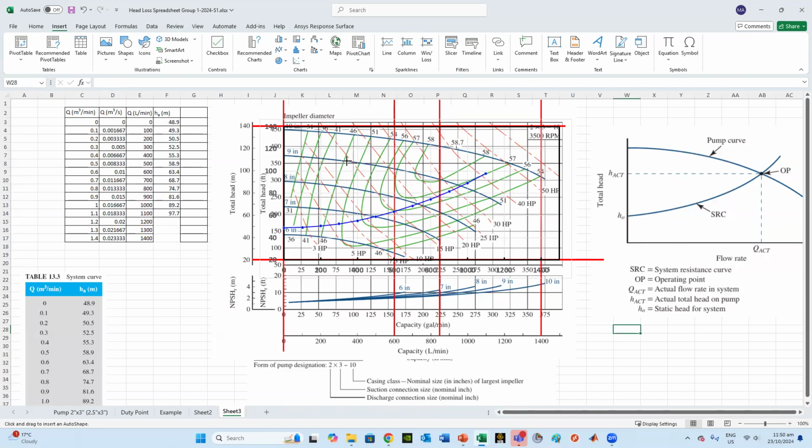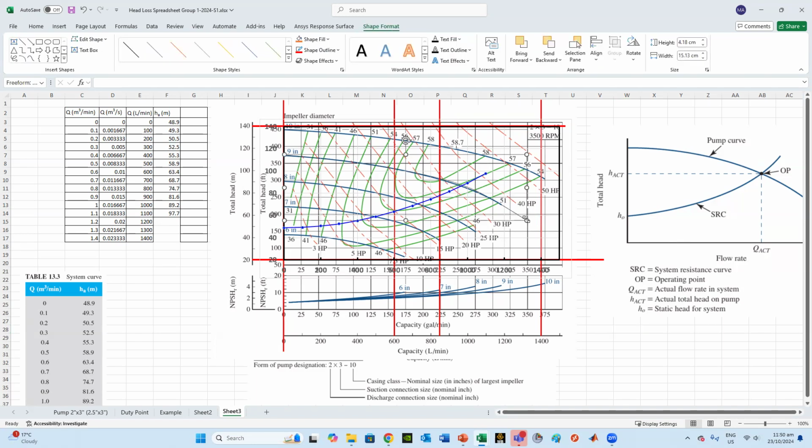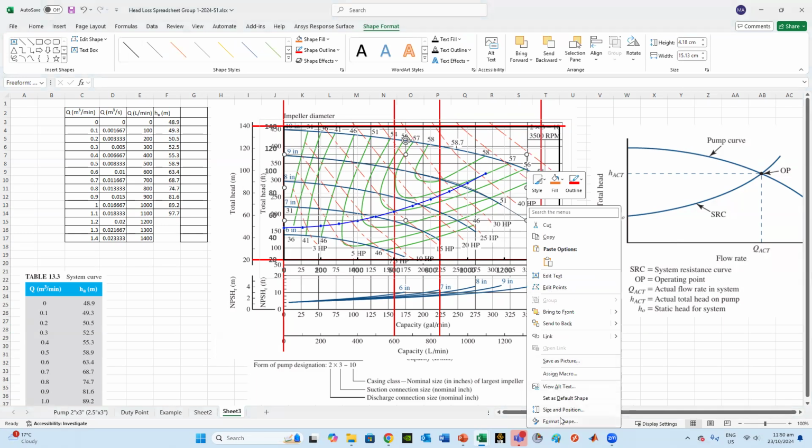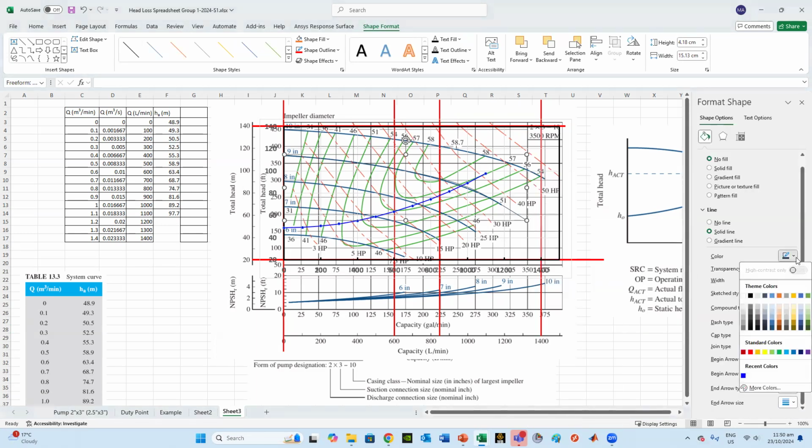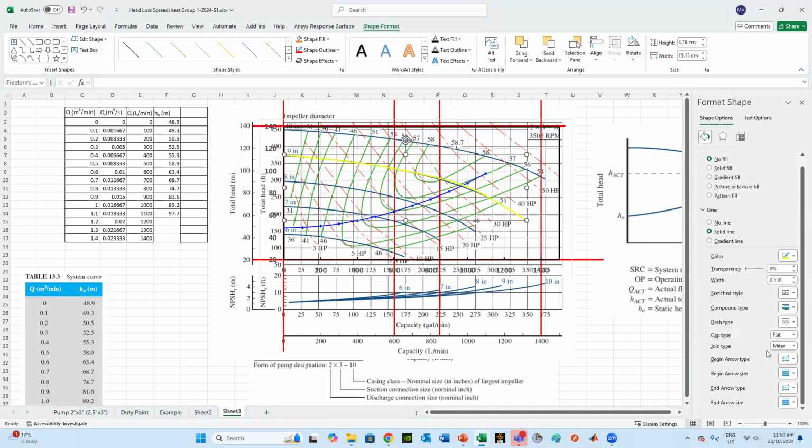And then you track the line which we are interested in, and then escape, and that one right click, format shape, change that shape to green, and then make it bigger. Oh, maybe green interferes with the original green, so give it maybe yellow. Not really. Choose something easy to distinguish. Purple is good. Increase the thickness just to show it going through it.